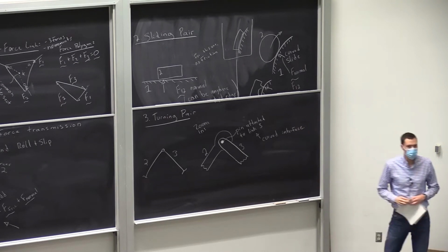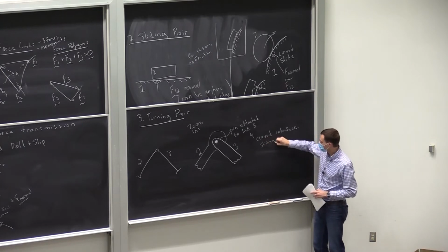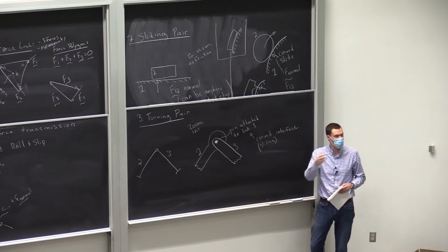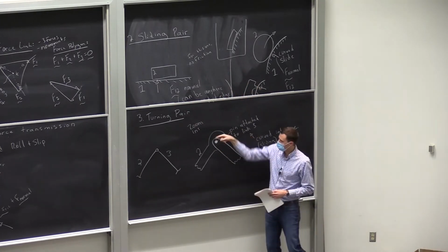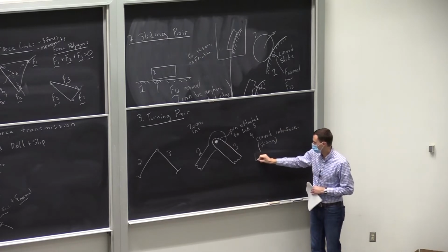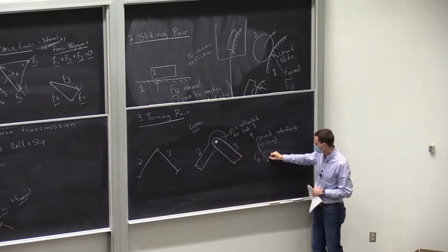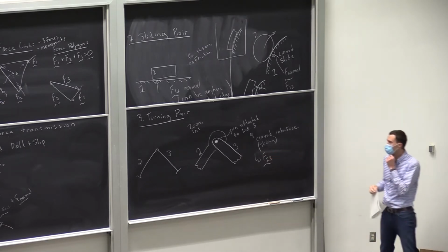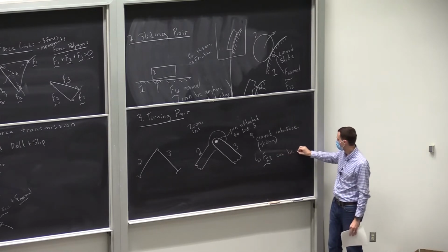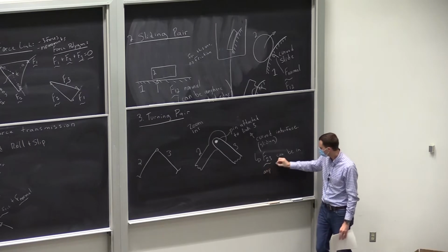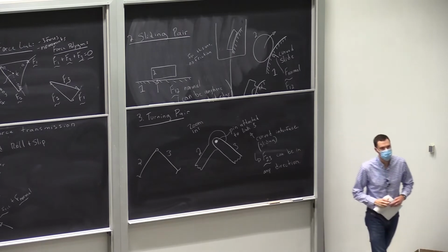Okay, and a curved interface, which is sliding, means the force can be transmitted in any direction. It has to be normal to the slide, but the slide is all the way around. So our conclusion here is that the force transmitted, for example F23, the force from 2 onto link 3, can be in any direction. Okay, and that makes sense.